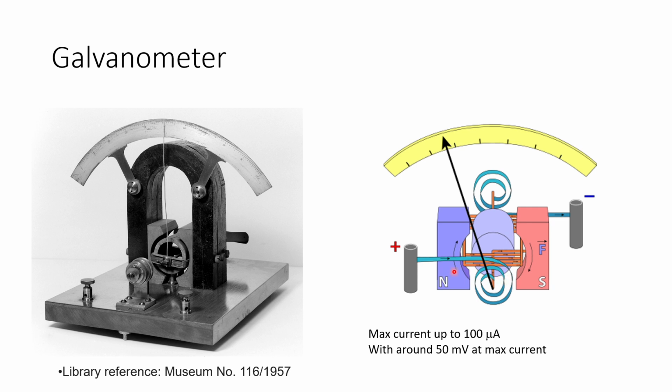multimeter technology. First of all, it comprises something very simple. Once you apply the current across this apparatus, you create a torsional force that drags the needle across the scale, and you can correlate that as the current going through the galvanometer. Or if you know the resistance of the galvanometer, you can use Ohm's law to calculate the voltage across